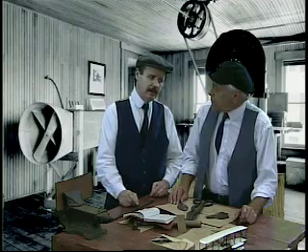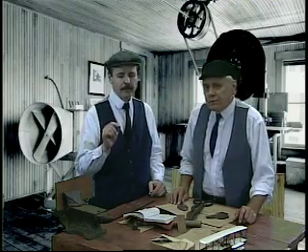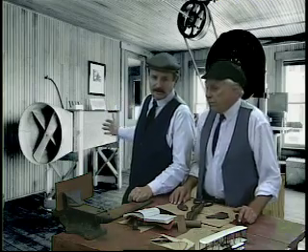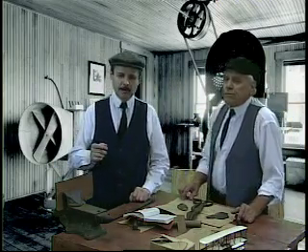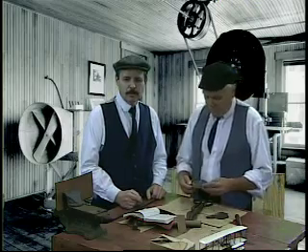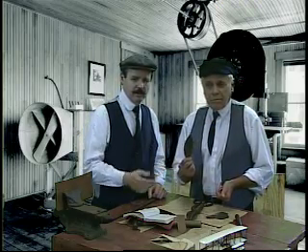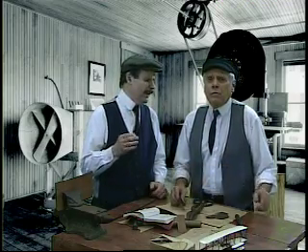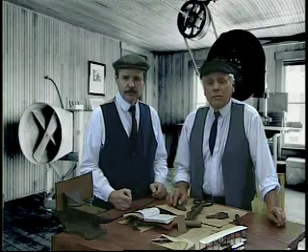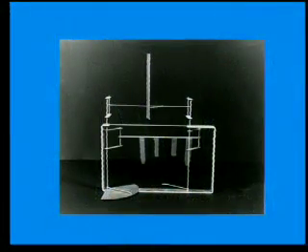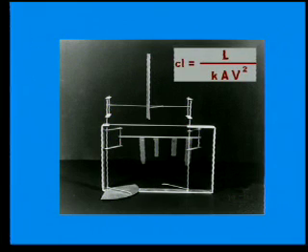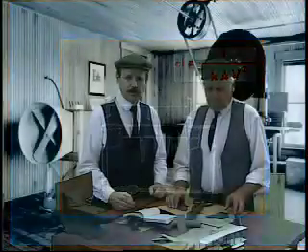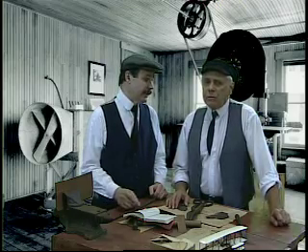After the 1901 glider with its larger wings only developed about 1/3 the predicted lift, we built a wind tunnel and began testing different wing shapes in there and different wing combinations. We used small metal shapes like my brother shown here to work on the wind tunnel. And there we could develop a balance. We used old hacksaw blades and bicycle spokes. The balance would measure lift. We knew the value of K, we measured the area, we measured the lift, and we controlled the velocity of the air through the tunnel, so we could now calculate the value of the lift coefficient. It turned out that our values did not agree with Lilienthal's tables.